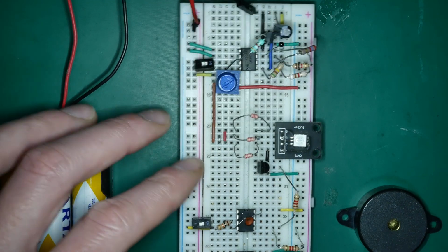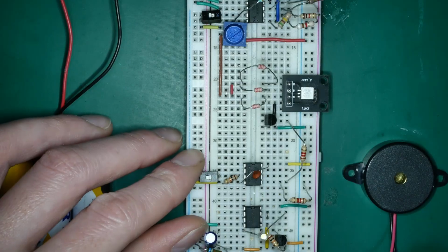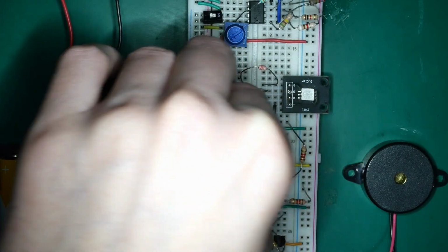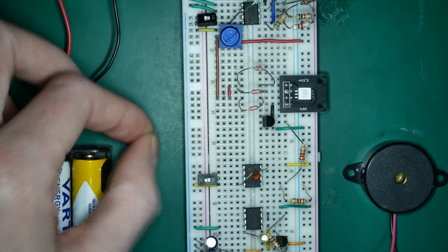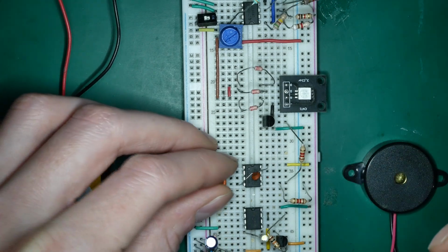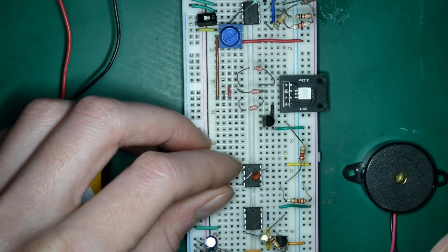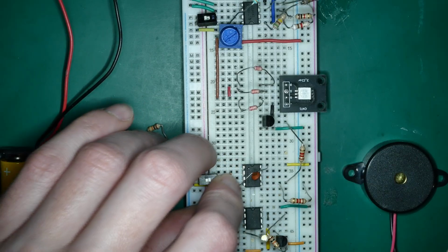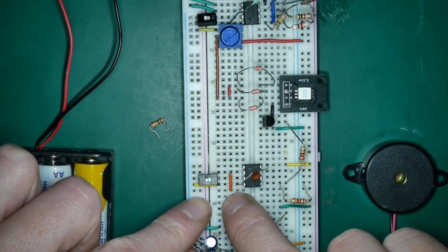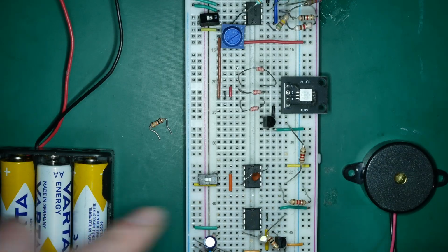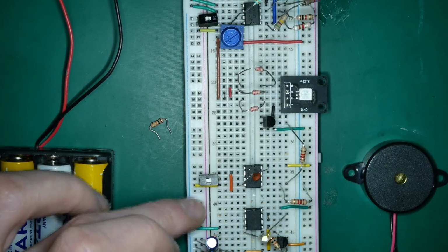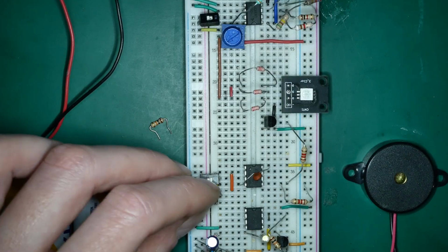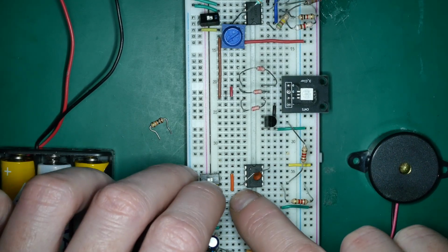The connection is pretty simple. First, I will take out the resistor because it's on my way. I will connect the jumper wire to the pin number 2 on the MCU and the empty line below the MCU. Now I will add a switch between the VCC and this empty line where I connected the jumper wire.